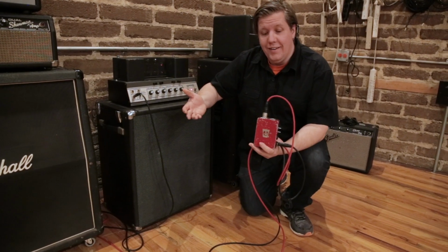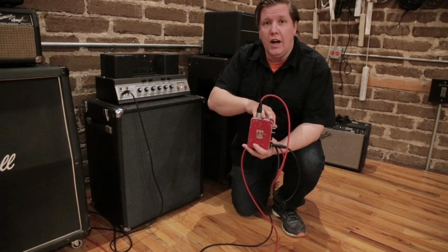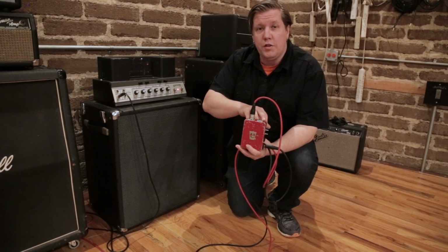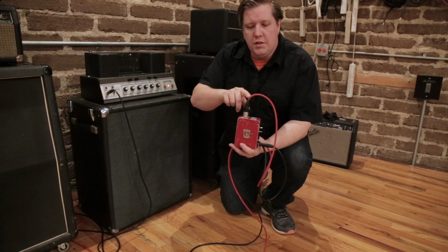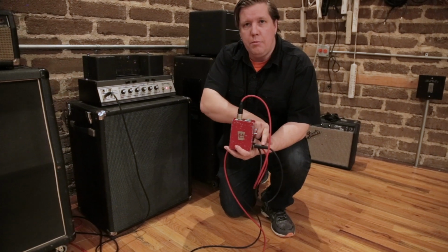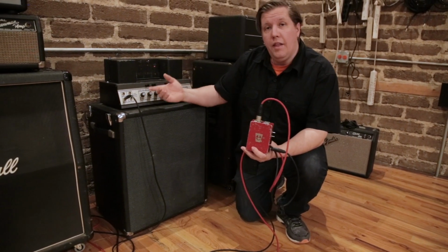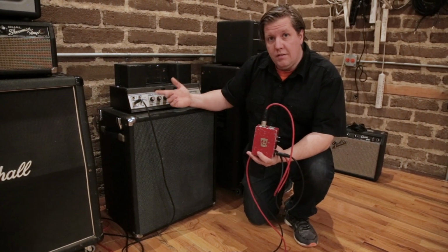So if we take our high impedance instrument level signal here, we'll be able to convert it to a low impedance balanced signal, meaning that we can maintain that signal integrity. But we're going to have to convert it back at the end of the line, so we're going to hook up another DI here. Because we're using identical DIs, we're doing essentially the reverse of what happened in the control room. So this signal is now being converted back to a high impedance instrument level signal, and therefore the amp sees a high impedance instrument level signal.